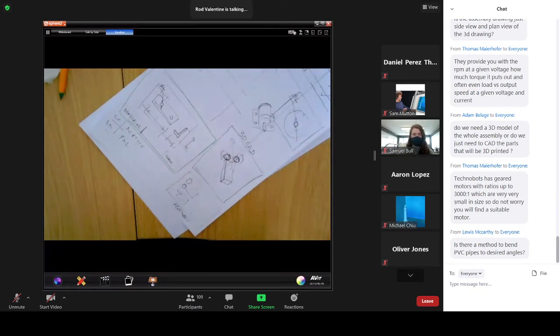As a standard rule, we tend to go for the front view, end view, and plan. But of course, you've got to manage the drawing sheet a little bit better to make sure that it all works. And then you can put on your dimensions. So that's the general rule. If we see a drawing that only has two views, we'll ask ourselves, can we actually see all of it? Can we see the basic mechanisms and understand the basic functionality of it?